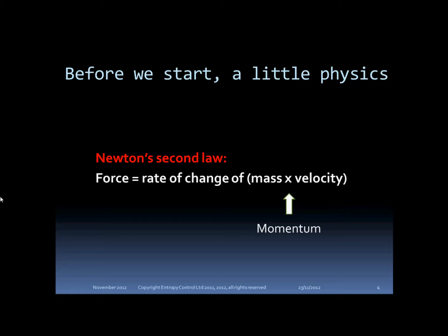If you have something hard to push against, force is easy. So pressing against a wall or a floor is easy and free. You can push as hard as you like against something rigid. But when you don't have a nice hard surface, you have to use Newton's second law to produce force by a change in momentum or a change in mass times velocity. Aircraft use this law to provide the forces that hold them up, and of course also to provide thrust.